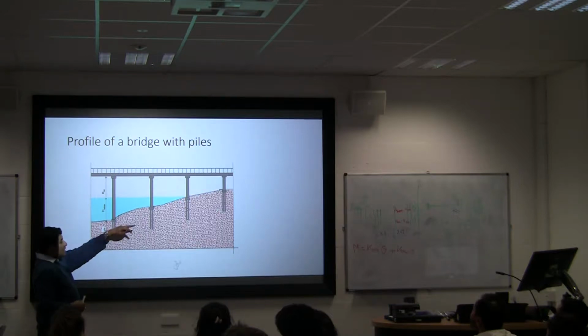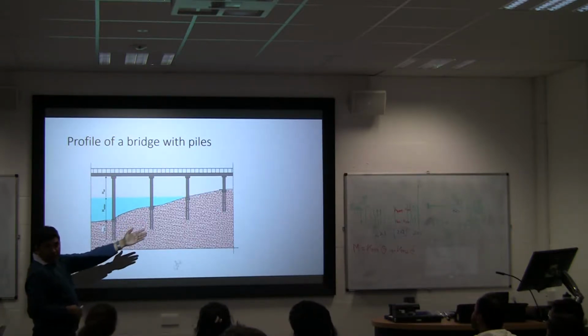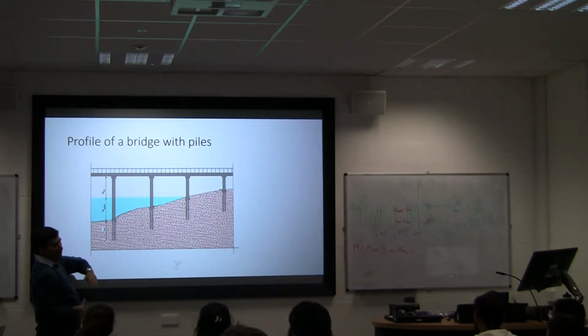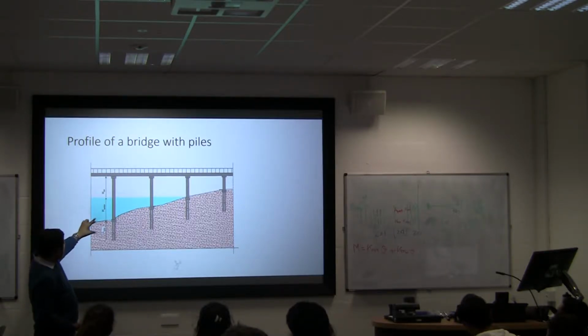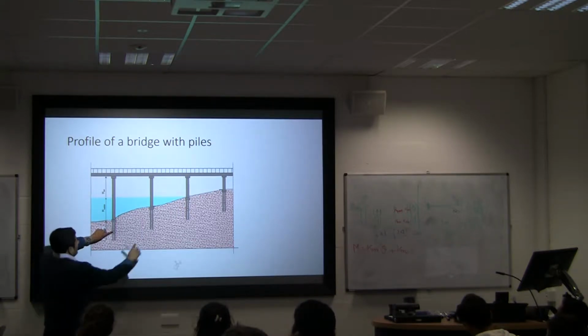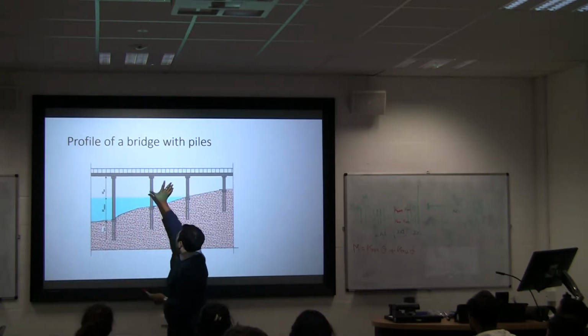What then happens in the middle of the bridge, they are all from earthquake cases where the ground liquefies. If the ground liquefies to a certain depth, what we can see is that this pile will be a whole lot more unsupported compared to this one, because in this case there were similar loads at the top.